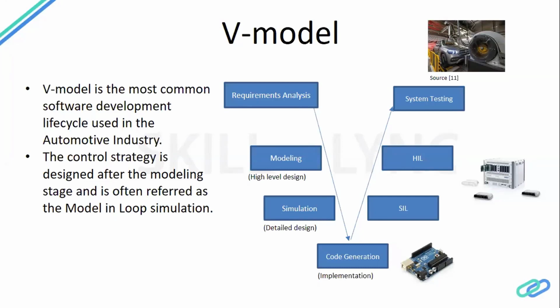But we are also focusing on the handling part today. So yeah, we can focus on vibration if our focus is on comfort. But for handling, we'll also focus on the displacement between the sprung and the unsprung mass, which is your suspension travel. And accordingly we'll move forward.